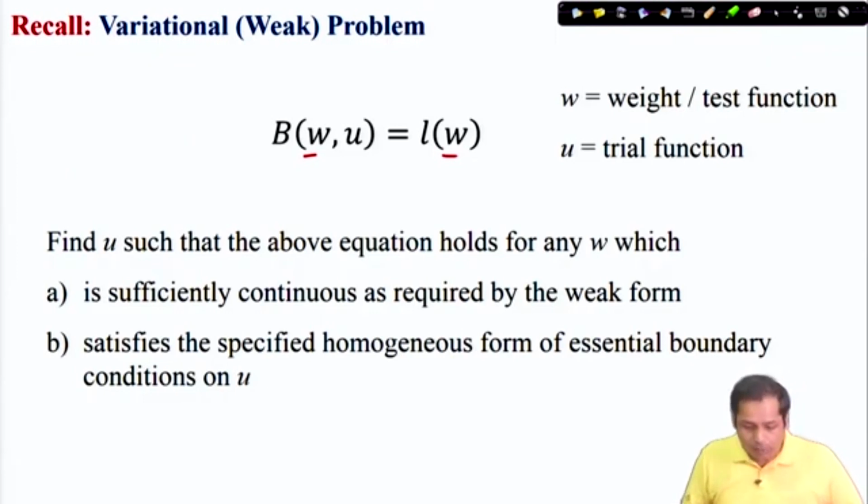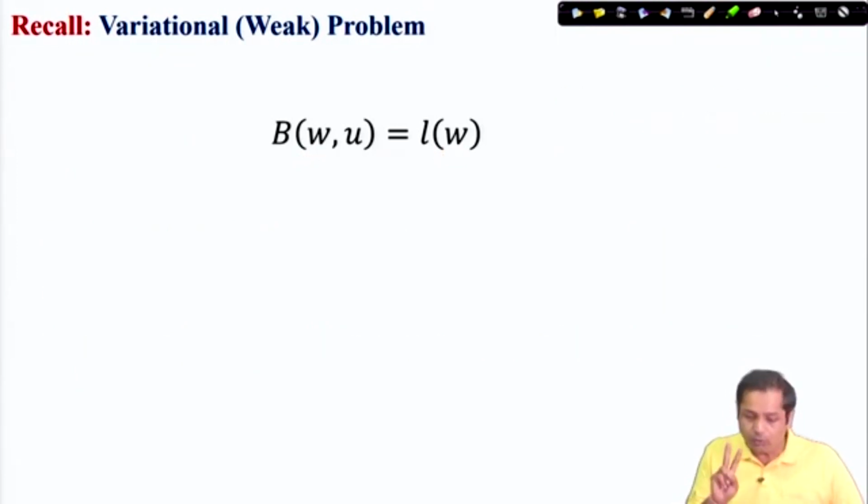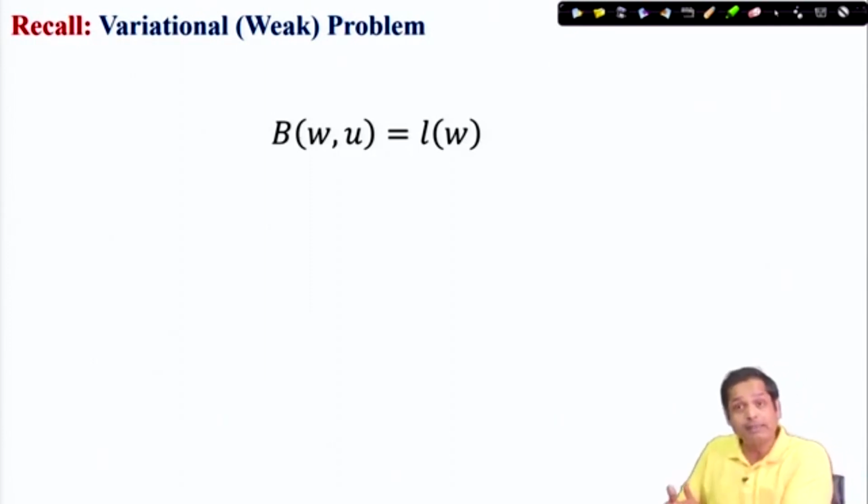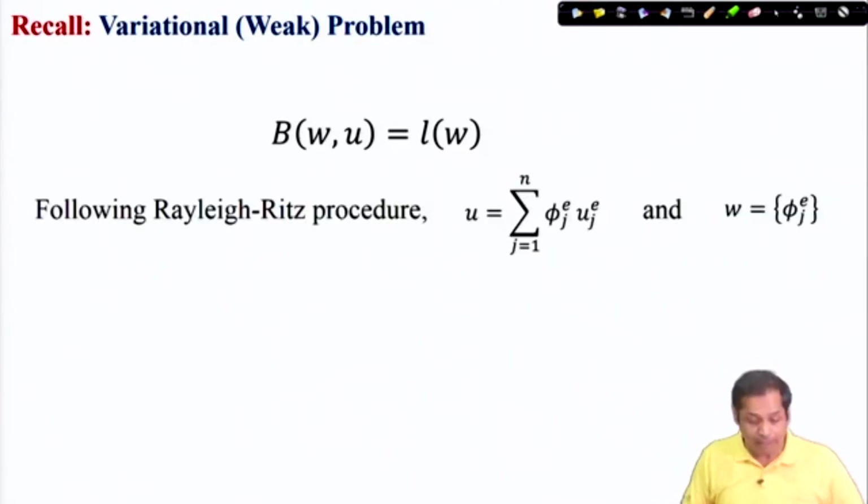Now what we do actually, there are two. Now this equation needs to be satisfied over every element. When we satisfy this equation over every element, we get a set of algebraic equations. We get n algebraic equations where n is the number of nodes we have in the element. Now from this statement, the variational problem, to finally getting the set of n algebraic equations, in between this, there are a few things that we perform. And what are those few things?